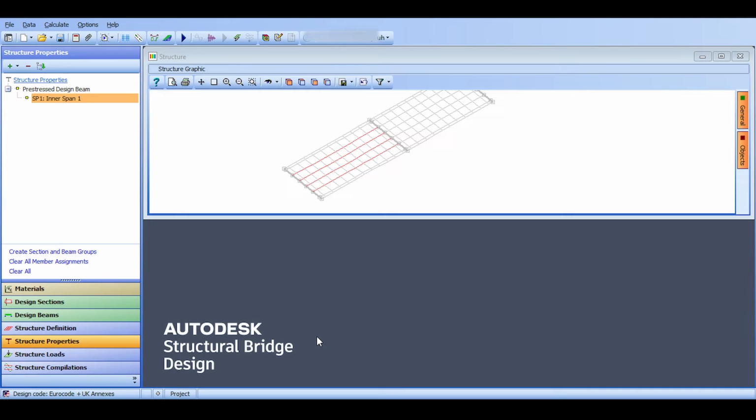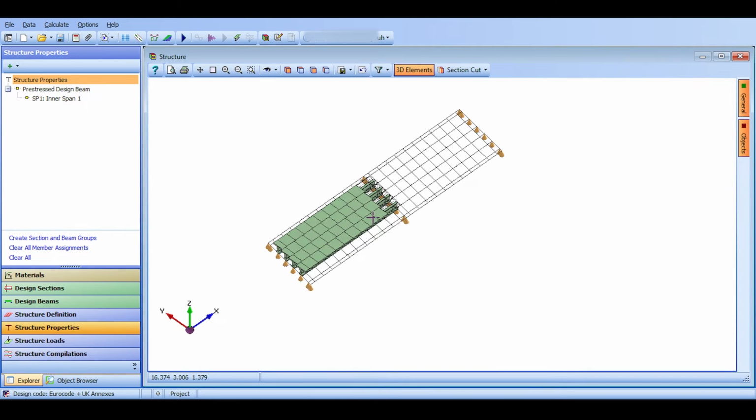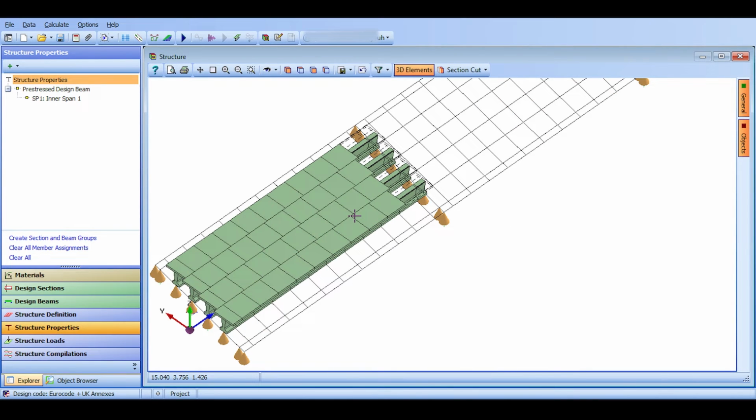And the magic has happened. You have 4 beams for the inner span. Now I will save first of all. And if I want to show them, you can click on this 3D view, or Control M, and then you can see them in 3D glory. And you can start seeing that the bridge is taking shape. Like this should cause joy in your heart.